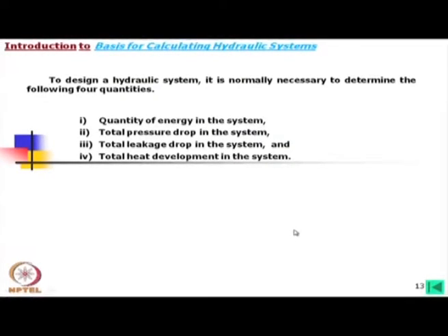Now, a hydraulic motor of that size can deliver maybe 20 kilowatt, whereas the electric fan is only 100 watt. The hydraulic motor of the same envelope size can deliver 20 kilowatt. So, that is why in many places it is very convenient to use such a system, although overall, if we consider the reservoir etc., it will be of huge size. Anyway, we should calculate all such things to predict the performance of a fluid power system.